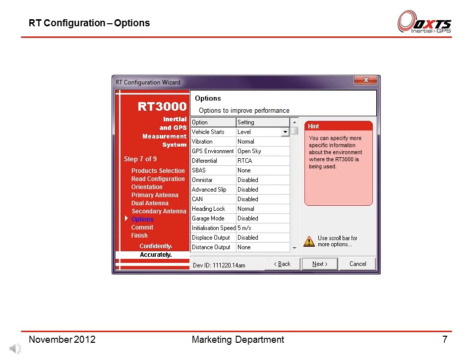SBAS. For SBAS enabled systems, the GPS receiver can be set up to receive corrections in North America or Europe. Because WAAS and EGNOS are in test mode, they can sometimes be unreliable. The corrections can be disabled by selecting None. For systems that do not have SBAS capability, this setting has no effect or is ignored.